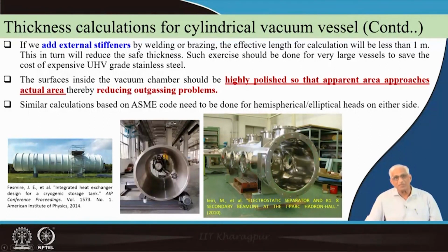Then you will take care of end plates, whether it is hemispherical or a door type thing with necessary gaskets. That and all we have seen in the last class, gasket materials, clamps, etc. So, a chamber, vessel, these are all you can change these words. Sometimes you call chamber, sometimes you call vessel, shell, etc. And sometimes in metallurgical furnaces, this entire chamber will be in another chamber where water circulation will be there, like a heat exchanger, shell. That time, the hydrostatic pressure, if there is any pressure, that has to be taken into account also, in addition to the atmospheric pressure.